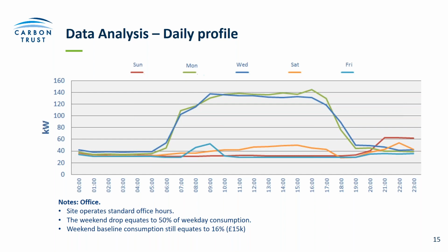And there's the curious peak on the Friday. I think that's probably New Year's Day, that Friday line. But it does pay you to try and work out why the profile is like that. Are things beginning to ramp up at the right time? Are there issues with BMS settings? All of those thoughts can be triggered by just looking at the profile charts.